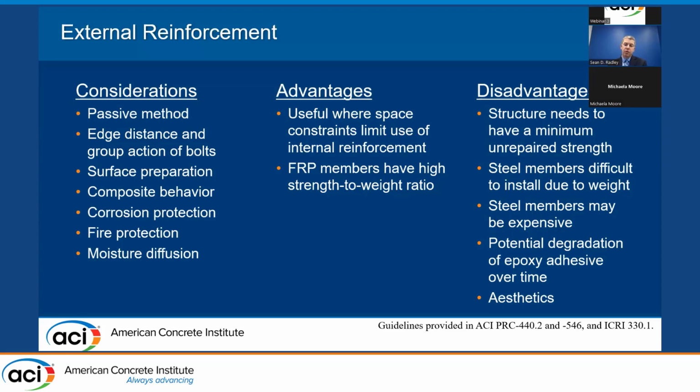If epoxy is chosen as the bonding technique, potential degradation over time may also need to be considered. And lastly, as with all external methods, aesthetics needs to be discussed with the owner and the architect because we're now changing the final look of the exposed structure. Further guidelines are provided in ACI 440.2, 546, and ICRI 330.1.